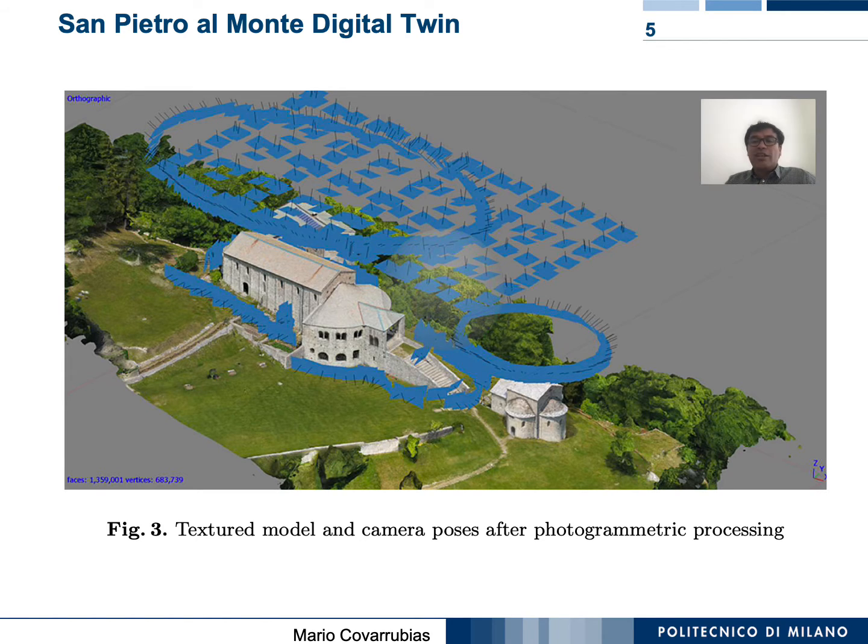So, the survey was conducted with a Parrot drone that is equipped with several sensors, with a very professional camera of about 21 megapixels, and a set of more than 200 images was captured in both automatic and manual ways. The automatic flight was planned with Pix4D Capture, obtaining a set of pictures with regular frontal and side overlap, which is enough for the reconstruction of the roofs and the topography of the area. Additional convergent images were acquired all around the buildings using both automatic and manual procedures.